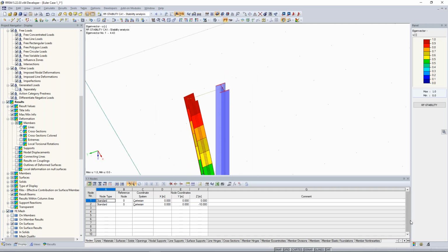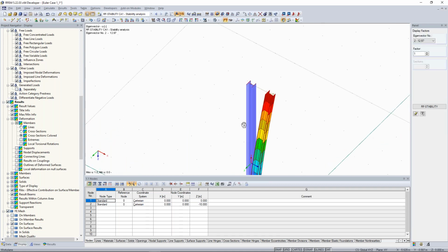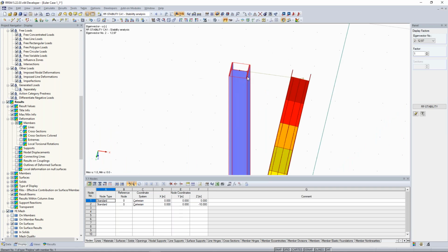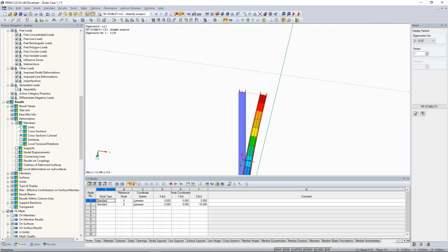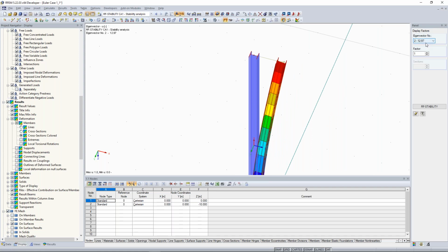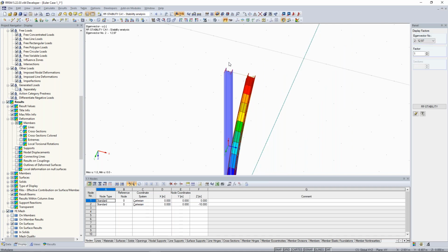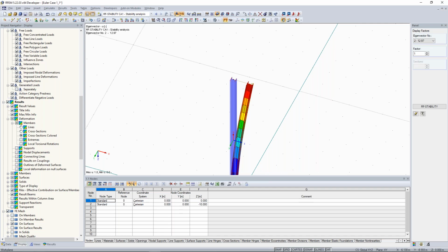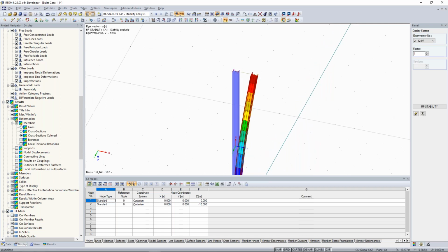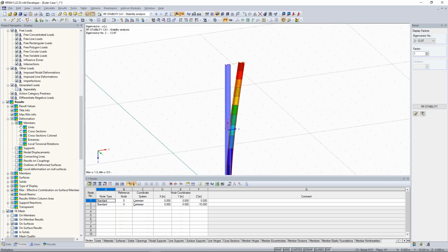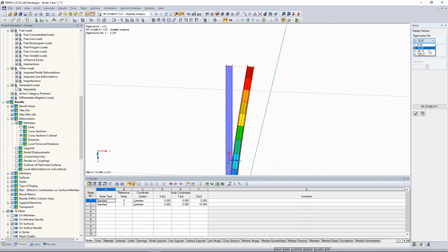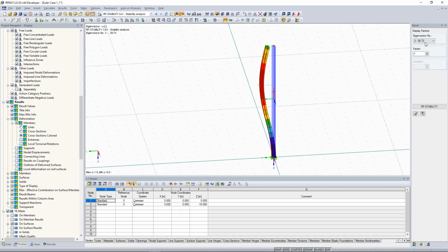When we jump to the next eigenvector, the second, this is a buckling around its strong axis. Here I have my flanges. This is the strong side. And here I have a critical load factor of almost 13. This would mean that if I multiply my 100 kilonewton with almost 13, then this would collapse around its strong axis. Yes, and also some other eigenforms and so on.